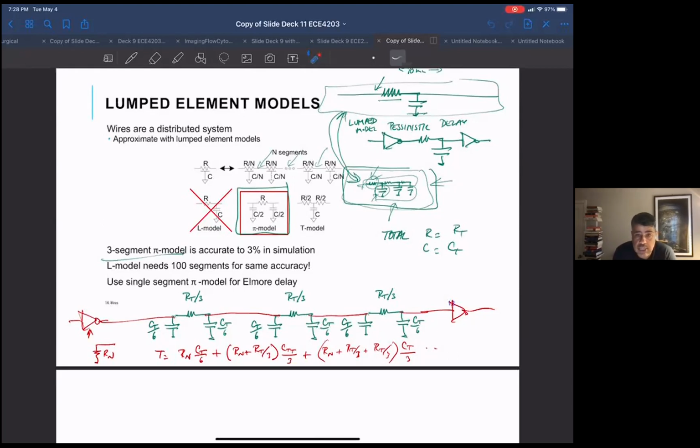Crosstalk is another thing that kills you in analog design, and also in digital design. You're a lot less sensitive to it in digital, but it still does affect you in long lines, etc. So the thing to visualize in this lecture is that the actual interconnects are just as important as the design of the transistors.